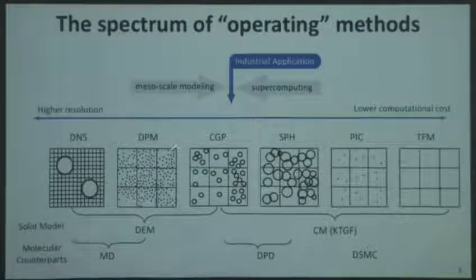So we still have the fluid flow solved at a scale larger than the particles, but the particles can be tracked as collections of many particles, and then it can go to the real commercial scale. But with this, we need a lot of information from the DNS level to provide the constitutive laws. So I think this DNS maybe is important because of this mesoscale scaling modeling need.